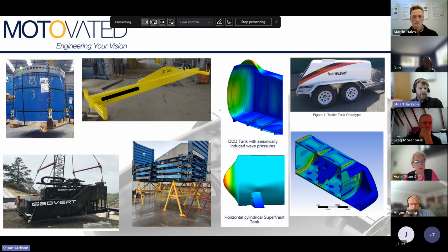So we would go along and take measurements of all the critical load carrying elements. We would come back to the office and run some calculations. We would make sure that it could take an overload test. We always run calculations, even on rudimentary pieces of equipment, just to make sure that when we do an overload test, we have a good confidence that nothing's going to fail. The last thing we want to do is take some piece of equipment, overload it, and have it fail and create some sort of other incident that is now adding risk. So we'll always do a little bit of calculation, even if we are going to ultimately test its strength with an overload test.